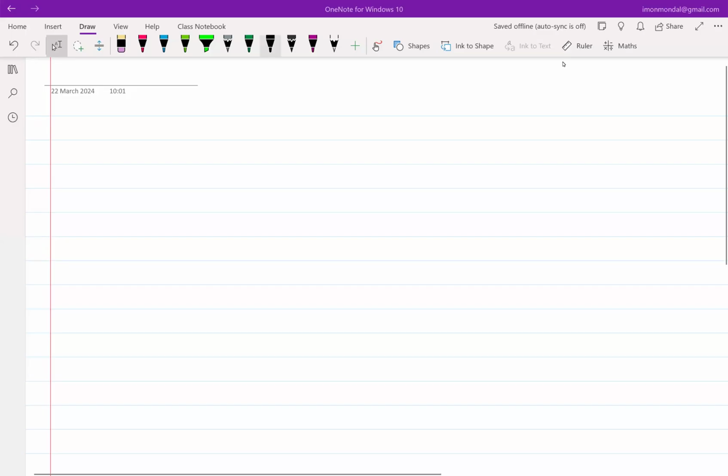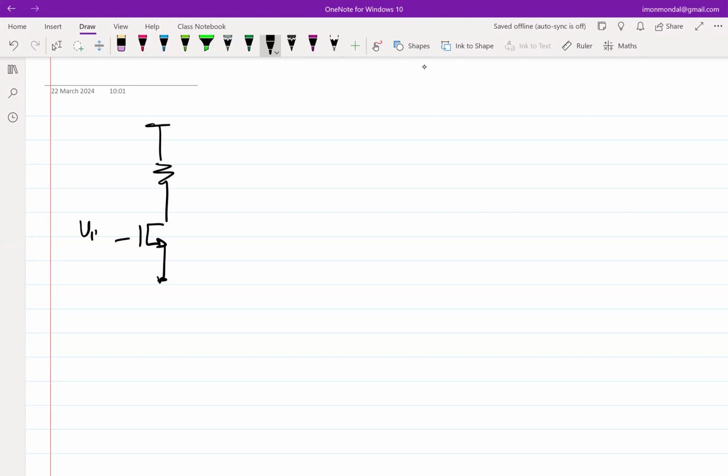So we were discussing the use of a current controlled current source to make a better common source amplifier, right? So what was the genesis of it? A 5-minute recap for the same is, so we knew that this is the structure of our common source amplifier shown without biasing. We have Vi, the incremental current gmVi flows entirely into the load and generates a voltage gmVi times RL, negative of that.